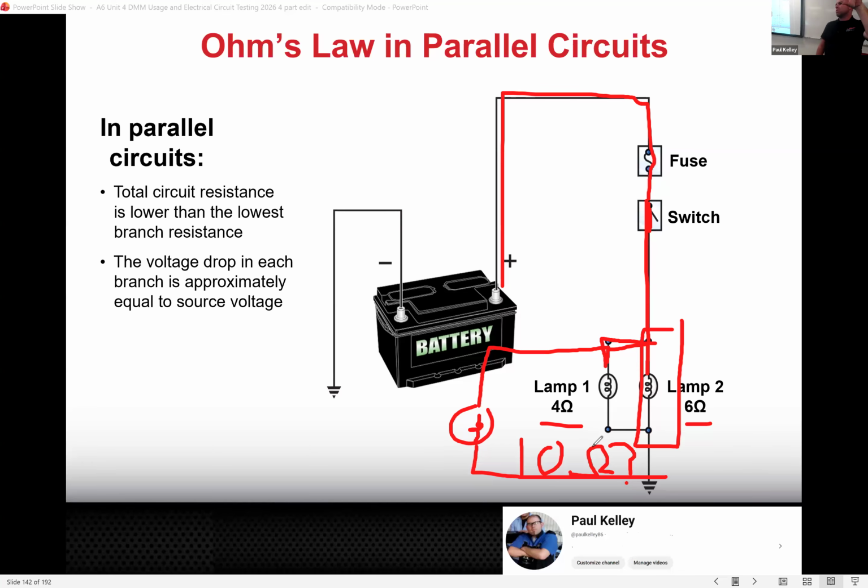We could know the voltage, and if we can calculate the amount of total resistance, we can determine the amps. Cool, I'll show you the formula, even though you'll never use it. But what I need to make sure you understand is if you keep adding bulbs on bulbs on bulbs, you're adding resistors, but you're actually decreasing the resistance because you keep adding lanes to the freeway.